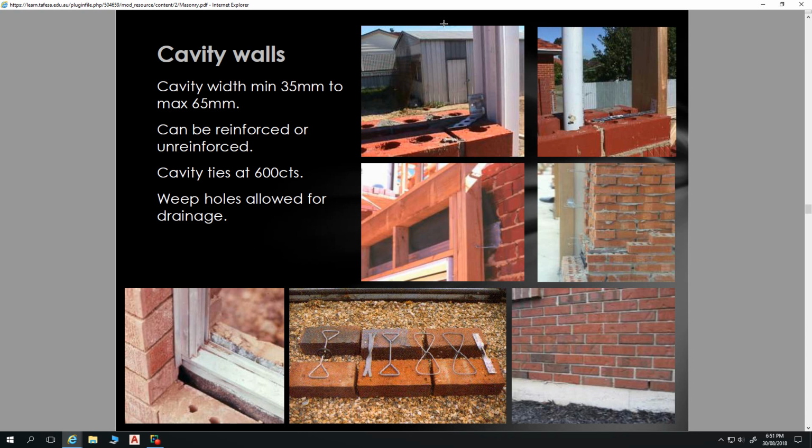But it was a much cheaper way of building a house than by building with brickwork and then rendering over the brickwork. But one of the telltale things to spot a blueboard rendered house as opposed to a brick rendered house was the brick rendered house still had all its weep holes down the bottom there. But yeah, that blueboard with render hasn't really shown itself to be a very good form of construction because you get movement in houses and cracking through the render at the joints of the blueboard.